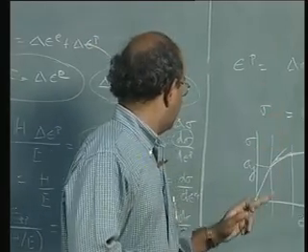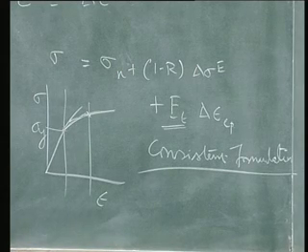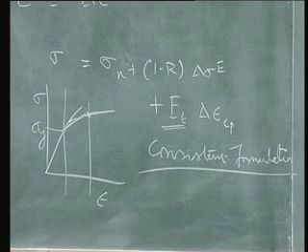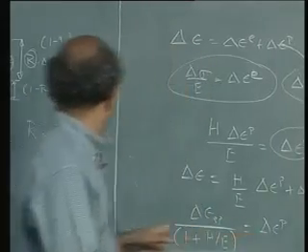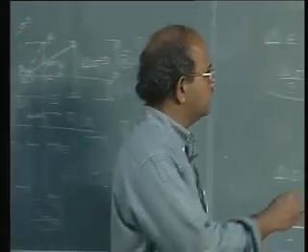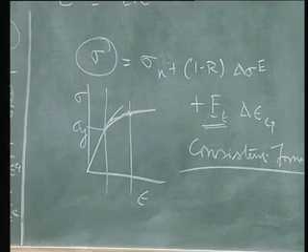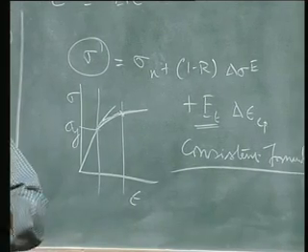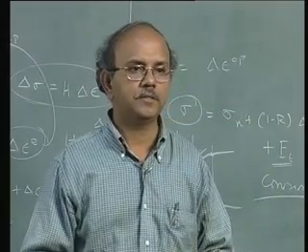Right. So, having calculated epsilon p, having updated it and having updated the stress, we go to the next iteration. So, we calculate now with the new sigma that we have done here. With this, we calculate the internal forces, look for equilibrium. This is a well established procedure, all of you know it. Look for equilibrium, look at the error, and then go to the next step, and so on.